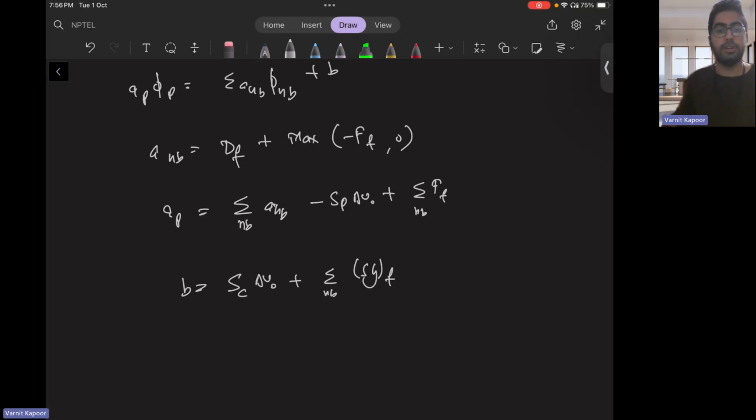Okay, secondary gradient values. If you again use higher order schemes for unstructured meshes, like we did for the structured one, you can say upwind third order, upwind second order schemes. What will happen? Again, you have to use a Taylor series expansion for unstructured meshes. So you can get a similar kind of scenario for higher order schemes as well.